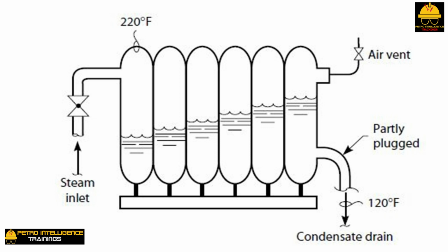It seems that 40% of the surface area of the radiator in the picture is submerged underwater. If the water is drained out, does this mean that the rate of steam condensation will increase by the same 40%? The answer is yes. Does this mean that the radiator heat transfer duty will increase by 40%? The answer is not quite.